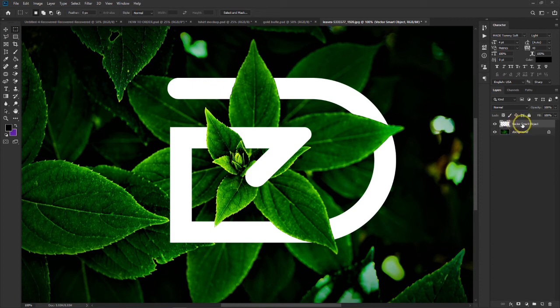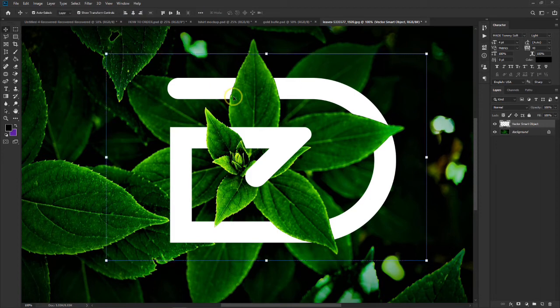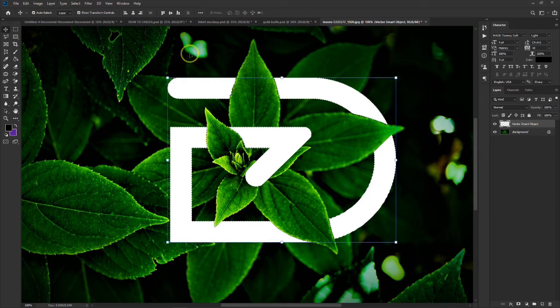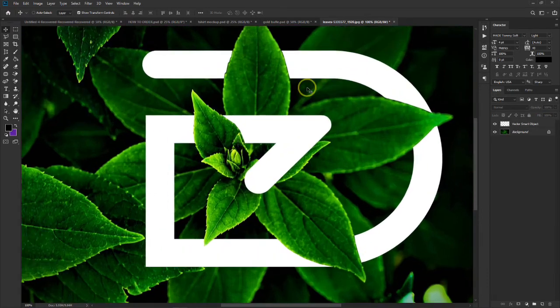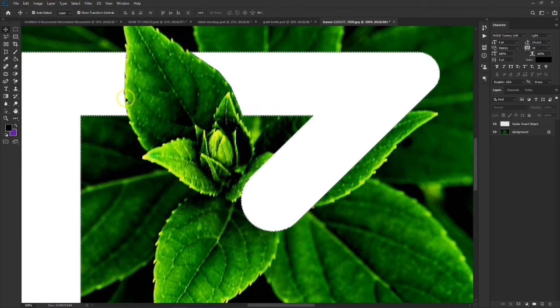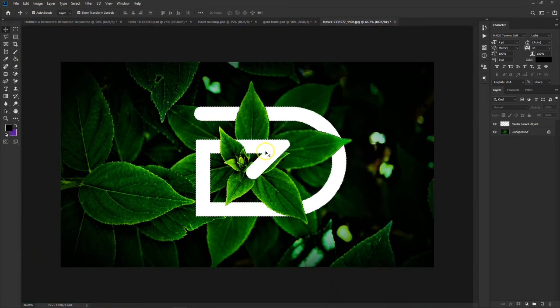We select the layer you want to select, then draw above it. It will draw something like this. Click on V on your keyboard, then click the arrow up on your keyboard. You know, arrow up and down and left and right. Just click on the up or the left or the right, any one you want. It will now select all that part in that particular layer. Okay, you selected, and you can see the edges. Let me zoom closely so you see all these things going on. It's actually selected that part, so that anything we are doing will be working inside it.